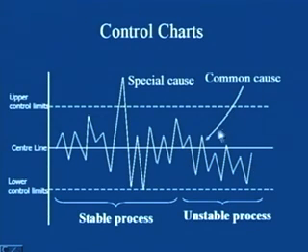When we see a decreasing trend, an increasing trend or a cycle while the data is within the limits, all those trends are basically because of common causes. There are some things we can improve. If this is a decreasing trend, maybe our tool is wearing out, or maybe the machine vibrations are increasing, whatever the reasons are.